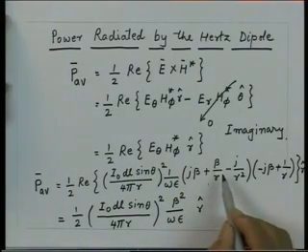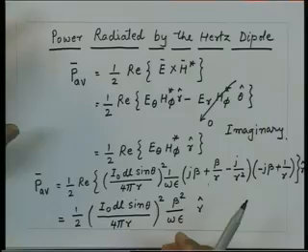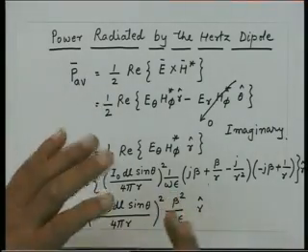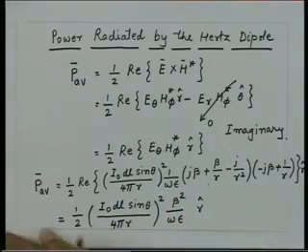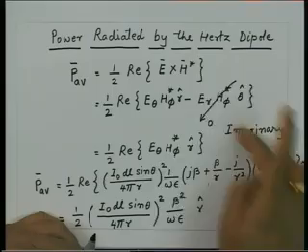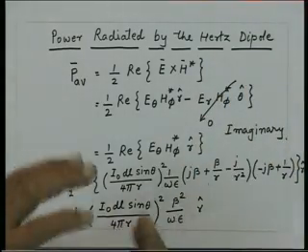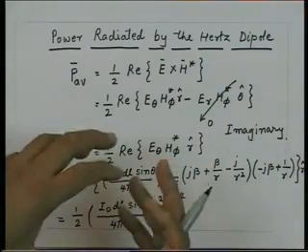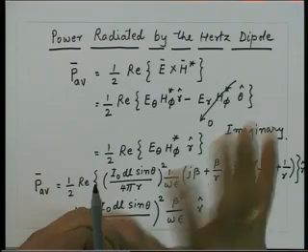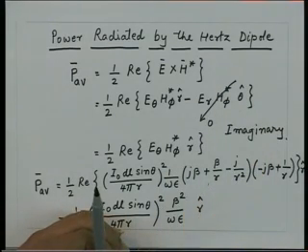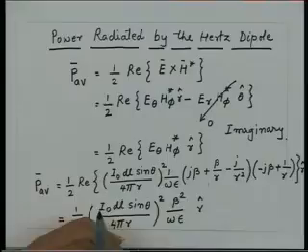So, essentially these components of the fields, they correspond to what is called the reactive fields. So, it is that when we are having this quantity purely imaginary and when you have 90-degree phase shift, it is as if we are having some kind of a reactive element there. So, in theta direction the power oscillates, either one half cycle in positive theta direction, the other half cycle in negative theta direction. So, the power keep oscillating, but there is no net power flow in the theta direction,